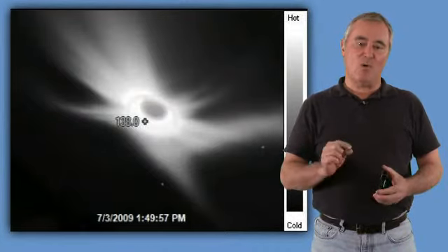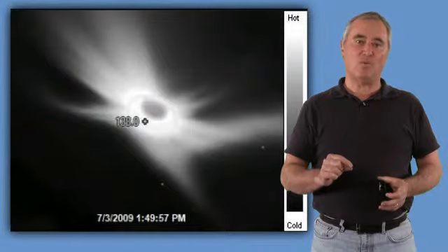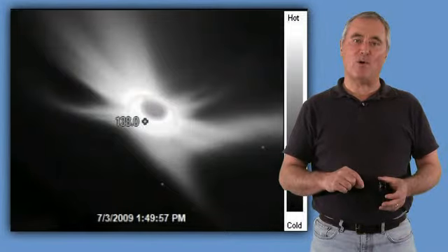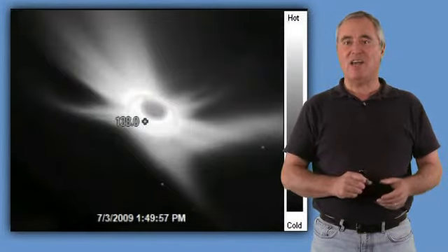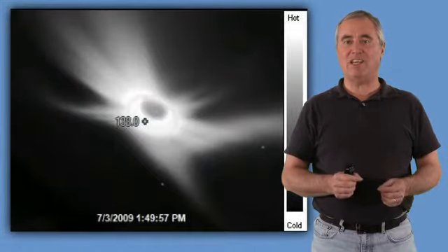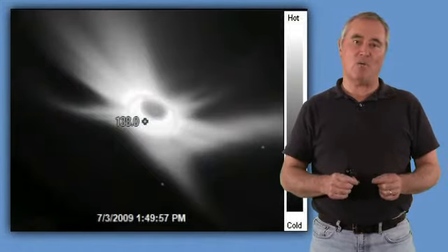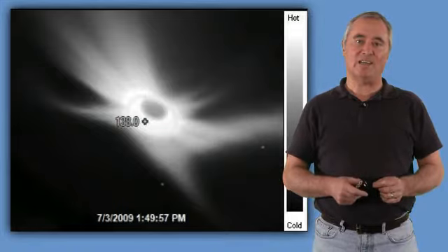And again, when we provide this feedback from the blower door and the infrared camera, it makes it much easier to find the leaks and much easier to train our workers where to look for the leaks and how to seal them.